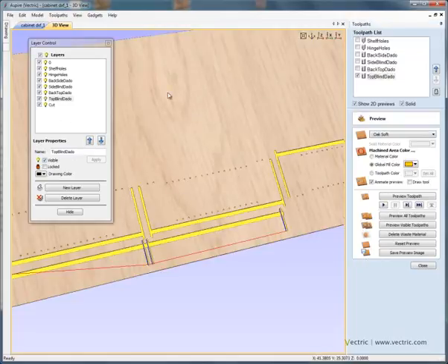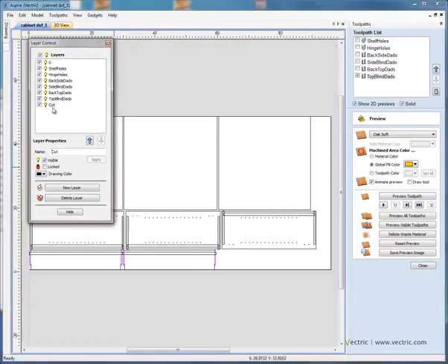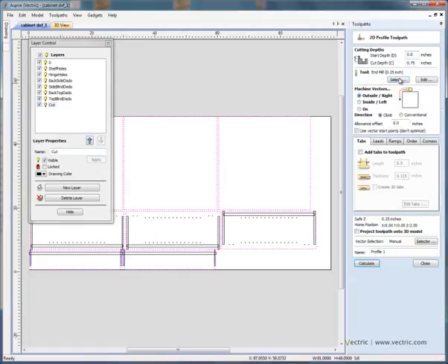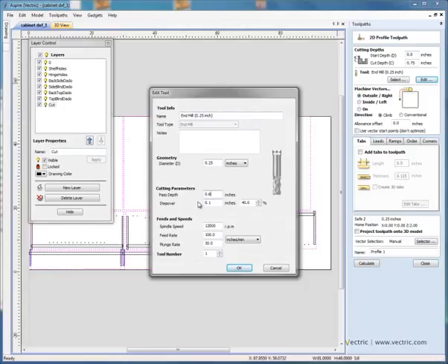And finally, we're going to cut the panels out. So to do that, 2D view, double click on the layer called cut, selects the required outlines, profile machine, around the outside, all the way through the 3/4 inch thick material, our 1/4 inch bit, and we're going to do a 0.6 of an inch pass, so it'll give us 2, so 0.6 then 0.75.